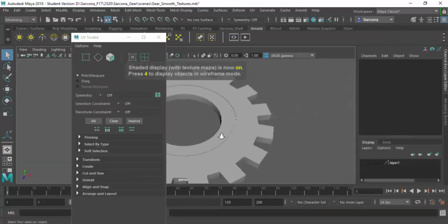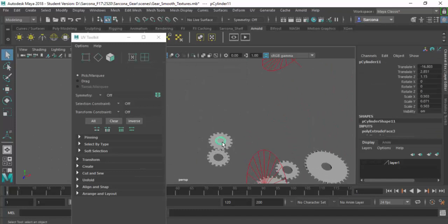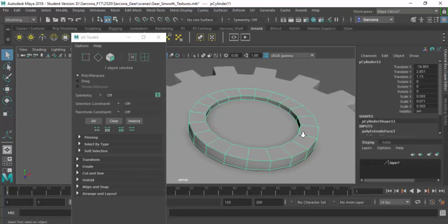All right, so cool. Where's my plug at right there? Okay, so same thing here. We want to add bevels to this. We want to smooth it out. So at this point, I would lay out the UVs. Then I would add my bevels. Then I would smooth it out. Okay? If you want fine detail, add the fine detail, lay out the UVs, and then smooth it out. Either one works. Okay?